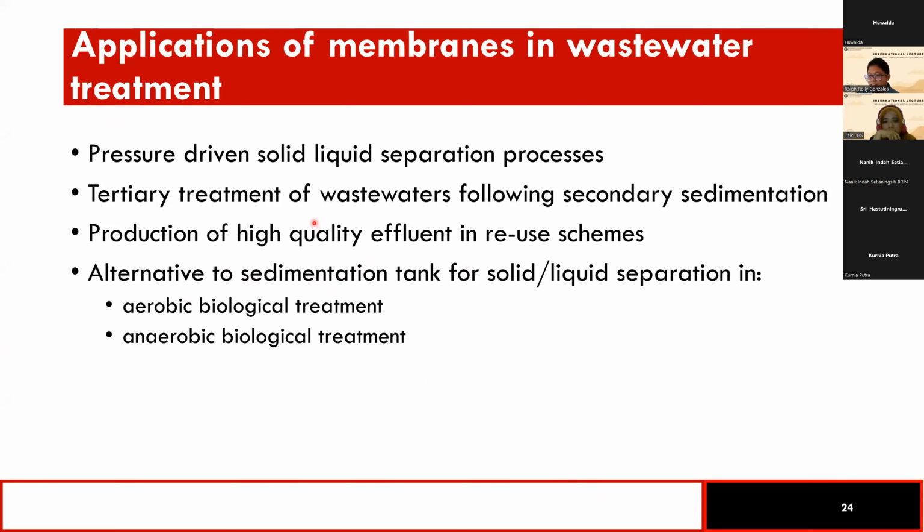But if we have a bigger scale membrane technology process, we can eliminate the sedimentation tank and just apply filtration directly. But of course, this will be quite costly because we'll have to apply pressure, we'll have to get membranes, we'll have to have a huge capital cost. And this